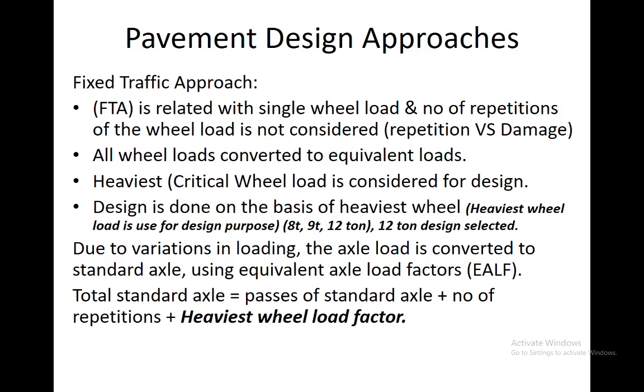So practically the pavement is subjected to multiple wheel loads, and for design purposes we also consider the multiple wheel load, which is again converted to a single equivalent load. So the heaviest load, for example, if we have different types of mode of operation such as 8 ton, 9 ton, 10 ton, and 12 ton, and so on. According to that specific method, we need to consider the heaviest wheel load, which is also considered quite critical for the design purpose as well.